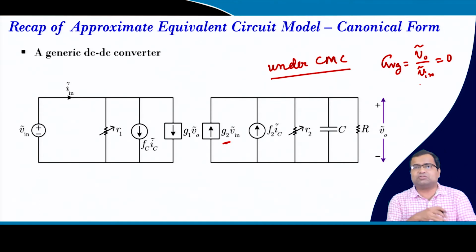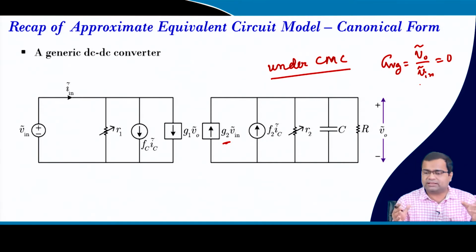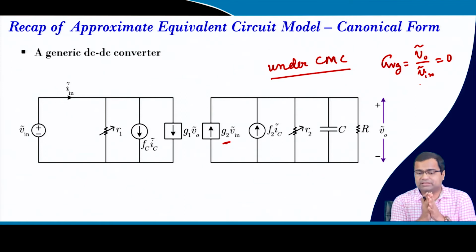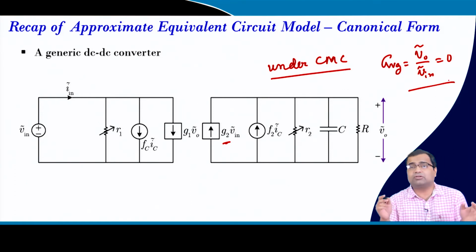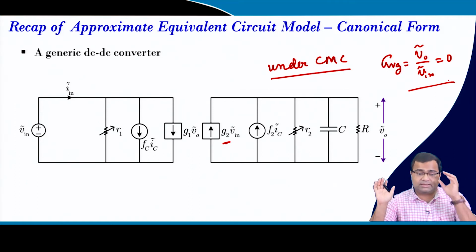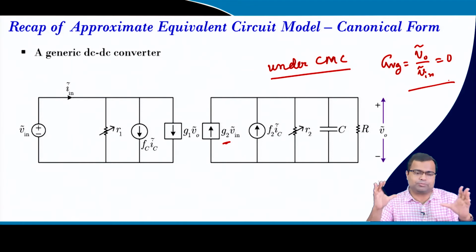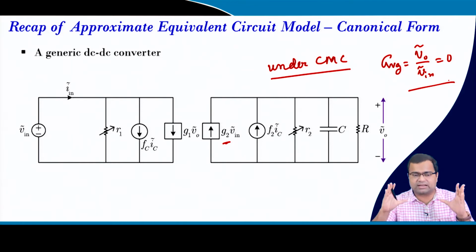It indicates there is no effect on the output voltage for a change in supply voltage. But it will not be the case for a boost converter; there will be a first order effect. Here we are only talking about buck converter model matching, because we have a separate lecture for boost converter model matching and current mode control design.